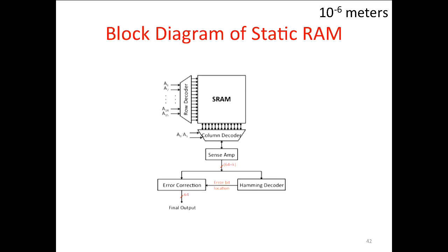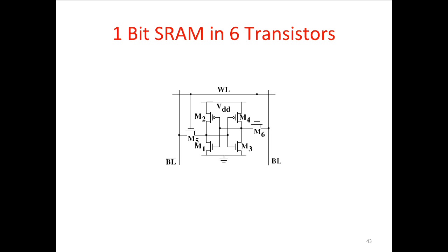So diving down into memory, so we talked about memory a lot. You have a lot of bits in an array. A single bit of SRAM takes 6 transistors, and this is the schematic diagram of 1 bit of memory, right, with 6 transistors. And what this is are 2 sets of inverters back to back. So you have inverters feeding each other, and that's stable if they both agree on where's 0 and 1. There's 2 possible states of that.